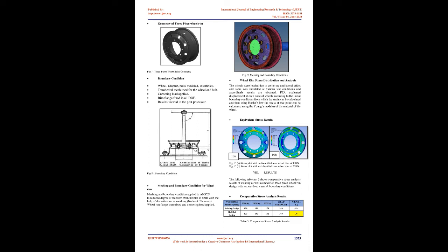Variable disc thickness to reduce weight, cost of the product, and new process of variable disc increased cold working effect on the product. Improvement in brake drum clearances. Adaptation of rim flow forming manufacture process. Flange shape optimization.